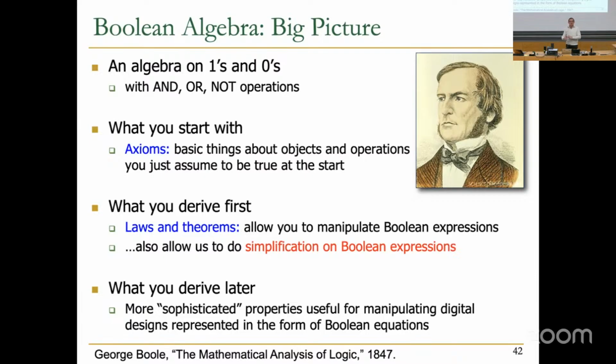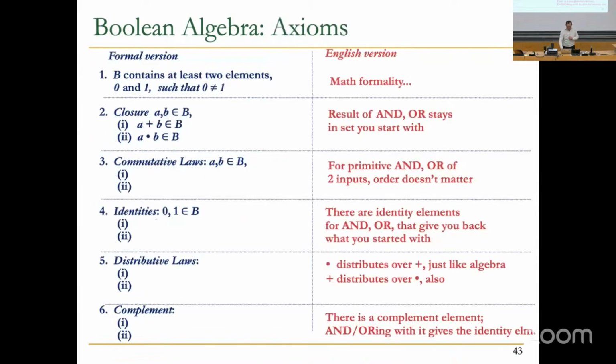And interestingly, this theoretical basis and all of these laws and theorems enable you to automatically design hardware and automatically optimize. This is called electronic design automation. You can specify a function, and that function is specified in terms of a truth table, and a computer program goes through that truth table and generates hardware completely. Of course, you can specify things at a higher level also, perhaps like a computer program, and as long as you can convert it to some truth table form, then you can actually design a circuit for it automatically as well. It's fascinating, I think. Okay, that's why we're covering it.